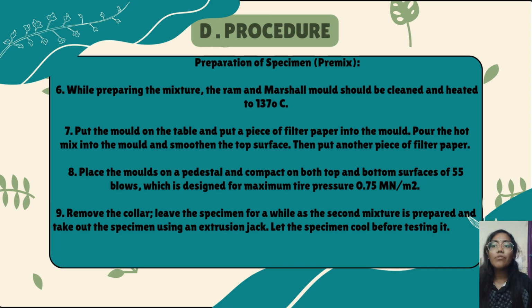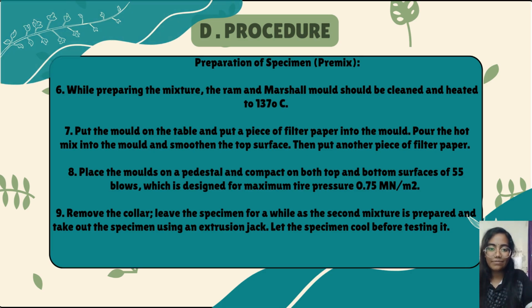Number 9, remove the collar, leave the specimen for a while as the second mixture is prepared, and take out the specimen using an extrusion jack. Let the specimen cool before testing it.